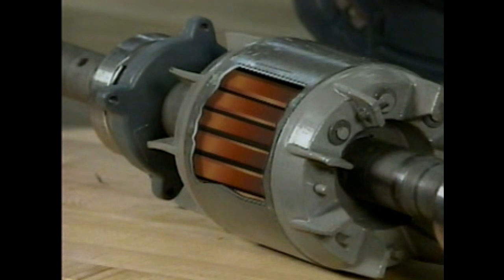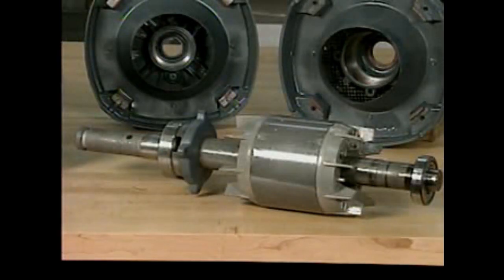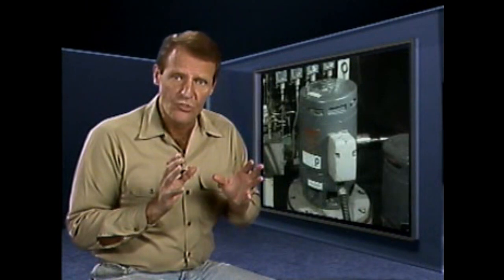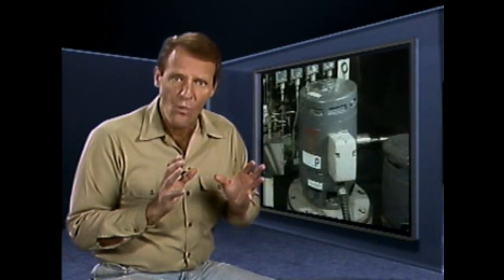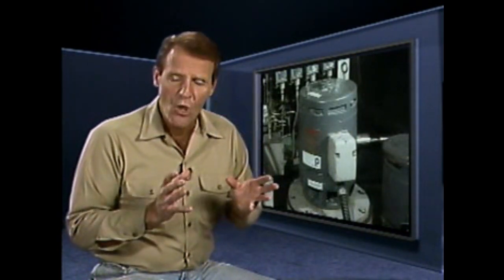This rotor is made of conducting bars that are shorted together by end rings. The rotor bars with their end rings are attached to a shaft so that the whole assembly can turn together. As the magnetic fields generated by the stator windings pass through the rotor, a voltage is induced in the rotor. The voltage creates current flow through the rotor, which creates another magnetic field. The interaction of the magnetic fields generated by the rotor and the stator windings produces motor action, which causes the rotor to turn.